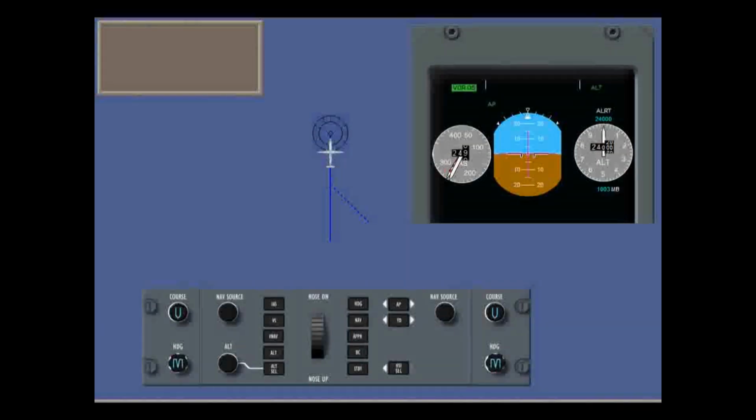In the zone of confusion near a VOR station, when the VOR deviation signal is very erratic, you may temporarily see the VOR overstation mode. In overstation mode, the flight director doesn't use the VOR deviation signal, but commands the aircraft to the selected course. The mode reverts to capture or track when the signal improves.